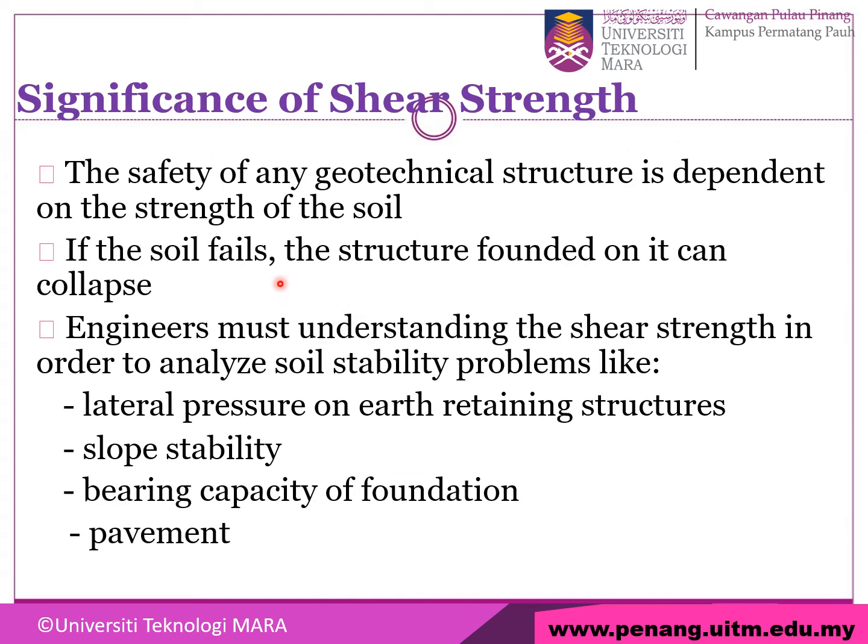Now we go to the significance of shear strength. The safety of any geotechnical structure depends on the strength of the soil. If the soil fails, the structure founded on it can collapse. Engineers must understand the shear strength in order to analyze soil stability problems like lateral pressure on earth retaining structures, slope stability, bearing capacity of foundations, and also pavement.